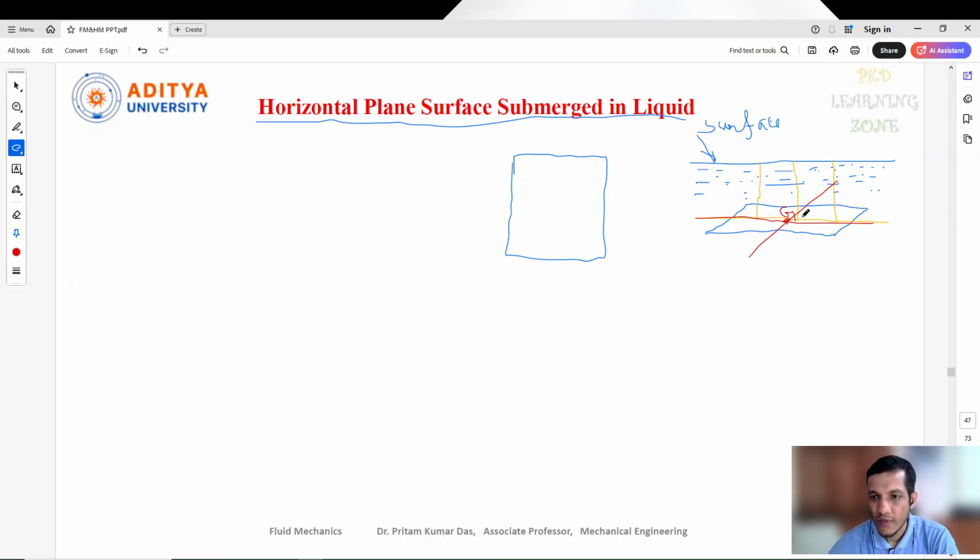Similarly, the center of pressure P point, or the pressure force, will be acting at the same point, because the distance from the surface is the same everywhere. So we can write the height from here to here as h bar, or the distance from the free surface to this P point as h star also. There is no difference, so both are at the same location.